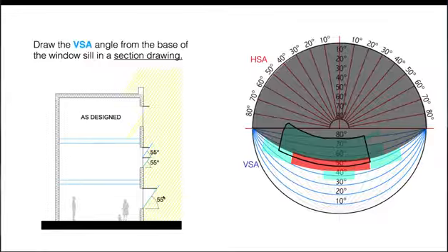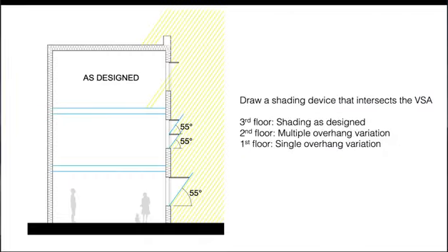And there's two different strategies to use this, or there's an infinite number, but you can use any number of overhangs. You can use 1, you can use 2, but it's necessary to note when you're using 2, you extend 1 halfway up or a third up, whatever it is, and then you extend the next one from that point on the window where that overhang starts. This is going to allow us to create an effective solar shading strategy for 55 and higher angle sun. Here you can see this is what it looks like now with sun coming in at 55 degrees and even at some smaller angles. Here we're blocking all sun angles higher than 55 degrees.